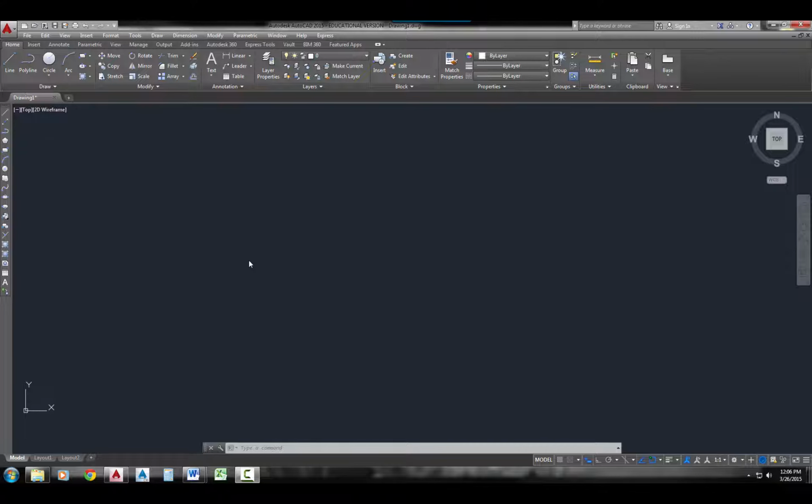The line command. I'm going to show you how you can draw lines using the AutoCAD line command. There's several ways that you can actually access the line command, so I'm going to show you 5 popular ways to do it. First, starting in release 2008, AutoCAD moved to having ribbons instead of toolbars. So this up here is an AutoCAD ribbon. I'm on the Home tab under the Draw panel, and I'm clicking on the line command.